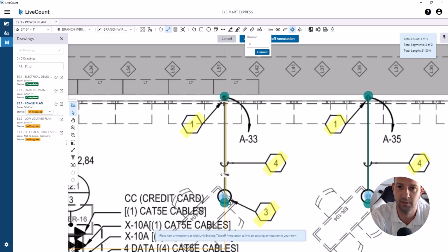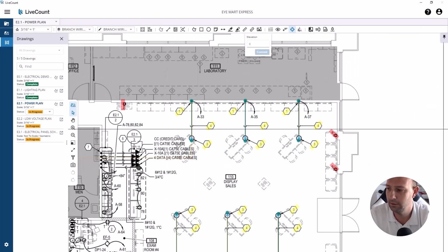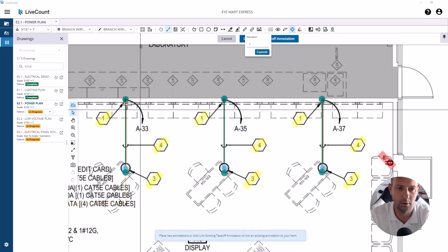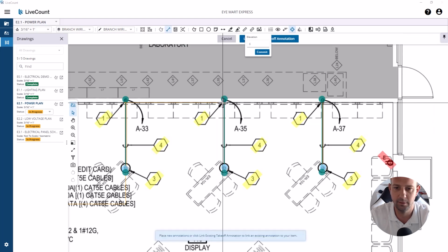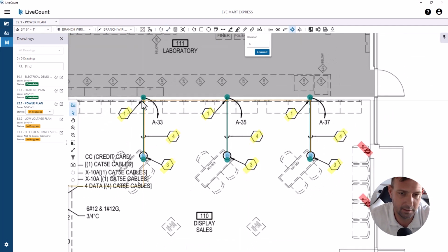So I'm going to say 6 feet to the home runs. A lot of people just say 10, but that would be just too much. So I got conduit over here to this home run. I'm going to bring another 3/4 inch with 5 number 12s down the wall, and then I'll bring another one with 3 over here. So now we know that we have wire to the top of the wall with cable.